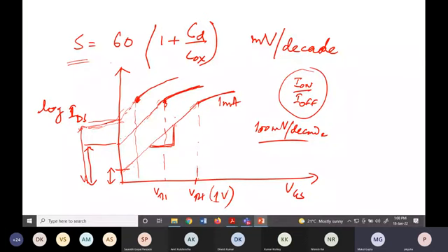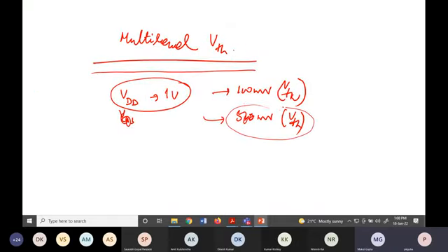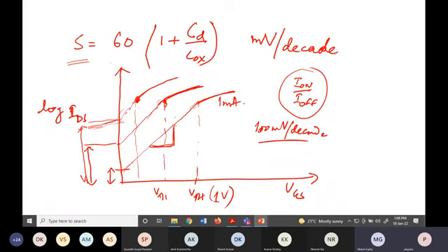In the chip there may be 1 million transistors, but you want faster operation from maybe 500 transistors. For those 500 transistors you have a threshold voltage of 100 millivolt, because you want them to operate very fast. But for the rest, the 9 lakh or so out of 10 lakh (1 million) transistors, you don't need much higher speed, so you use a higher threshold voltage. You fabricate with higher threshold voltage, so that will reduce the leakage current.